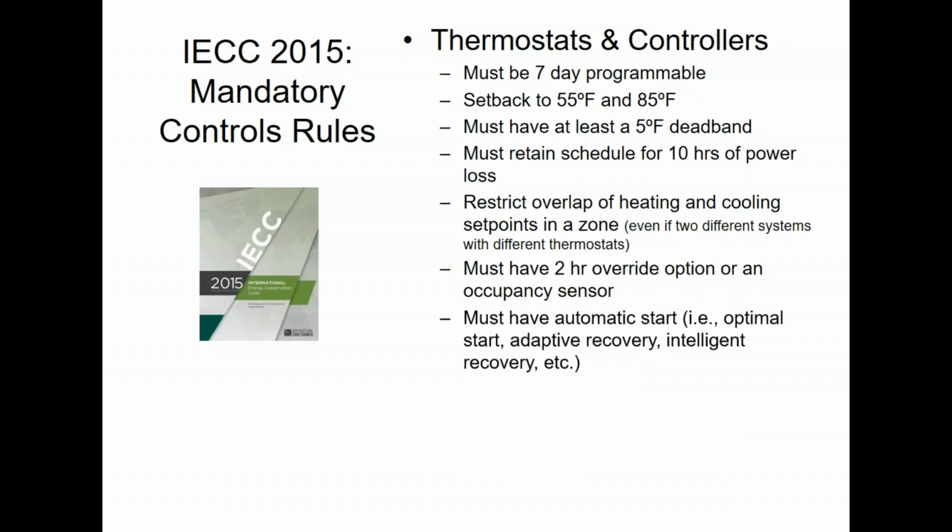The thermostat has to have, or the controller, if you've got a DDC controller, same thing, the thermostat or the controller has to have an optimal start routine. There are numerous different names for that out in the market. But basically, the system starts calculating when it needs to begin heating and cooling in order to have the space at set point at the time you say it's going to go occupied. So if you say it's going to go occupied at 8 o'clock, you would set it for 8 o'clock, whereas with a regular stat, you would set it for 6 or 7 in the morning. This one you would still set for 8, and the stat would calculate, oh, I need to start at 7:23 today, so it's the perfect temperature when Ryan walks in the door.